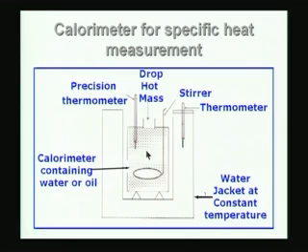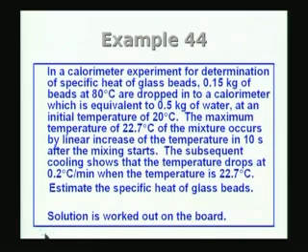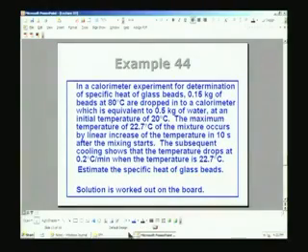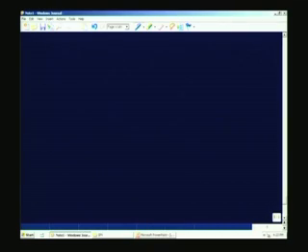The initial temperature of the calorimeter as well as the water jacket will be the same, which we can refer to as T1. The temperature of the mass which is being dropped can be taken as T3. Finally, the temperature of the calorimetric vessel goes to a value equal to T2. So, these are the temperatures we are going to be interested in. Once these temperatures have been measured, I can estimate the specific heat of the material. Before we go to the example, let us look at the theoretical background required for explaining the method.